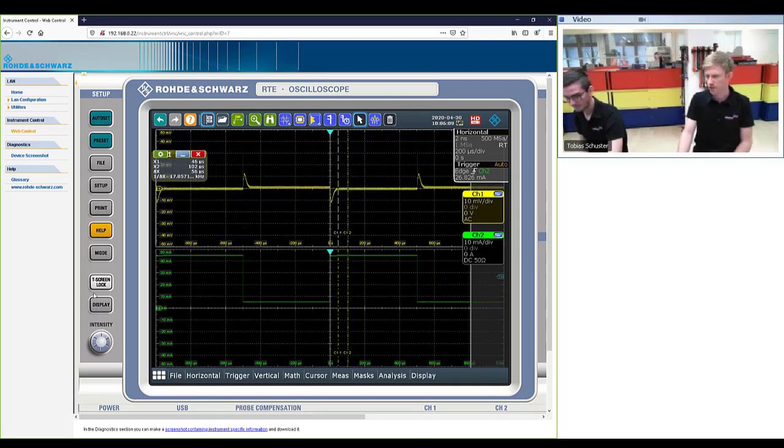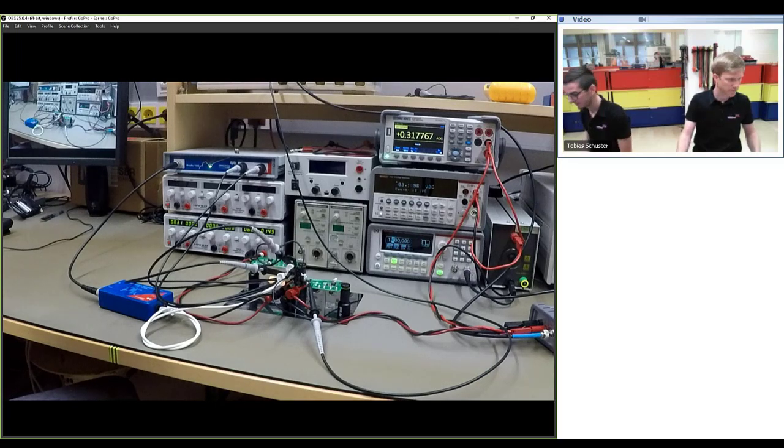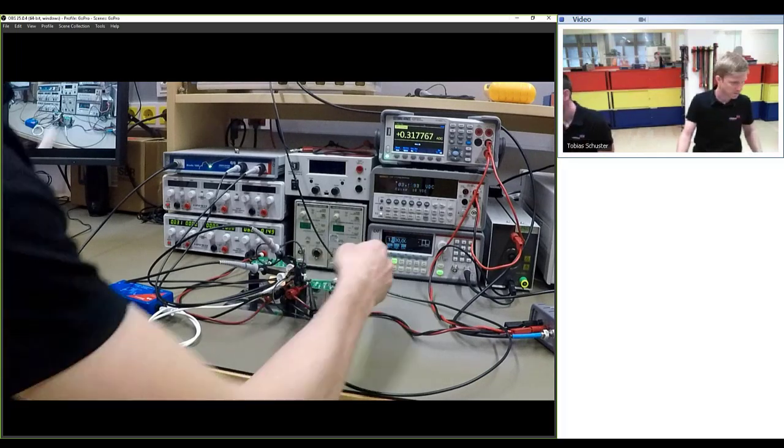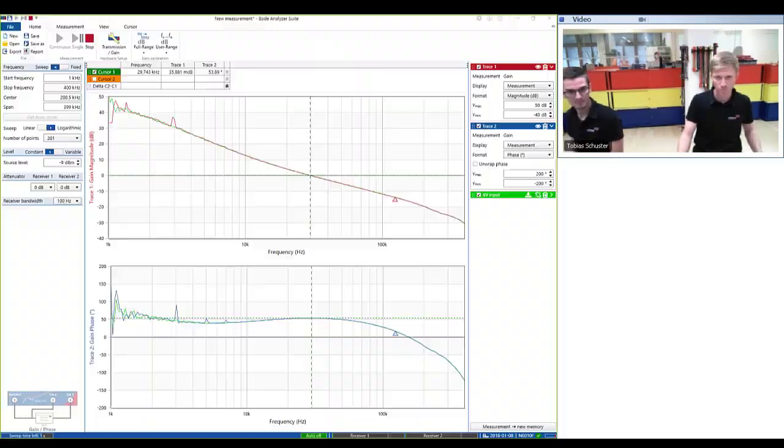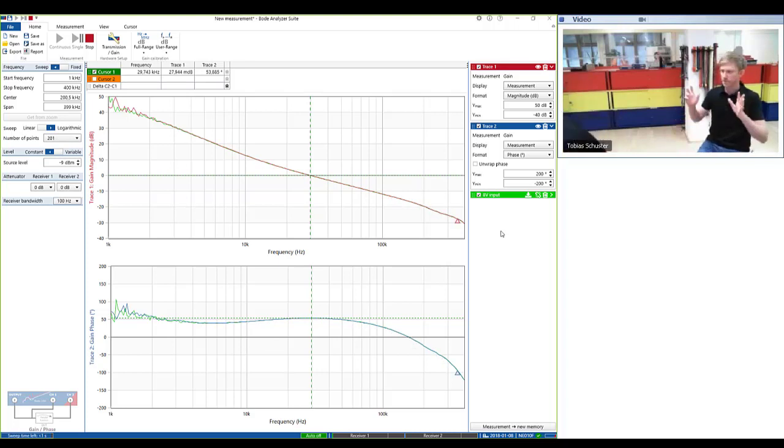So we're going to go back to the loop gain measurement. Can you please connect the injection transformer again? And then take off the load stepping, because otherwise our measurement will be pretty noisy. So now the load stepping is off and the measurement is running again. And now we know that we have no input filter connected. Yes, and now we're going to connect the input filter.